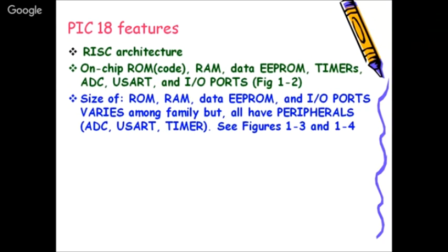So in RAM space, there are basically two kinds of registers. One is SFRs and the other is GPRs, general purpose registers. So the file registers of the RAM comprise general purpose registers and special function registers. Every controller will have special function registers for sure. Your general purpose register memory may be restricted. So 128 bytes are there for special function registers, and the remaining 128 bytes are generally used for scratch pad or working area. But in case of PIC, you have a large, wide working space, scratch pad available.